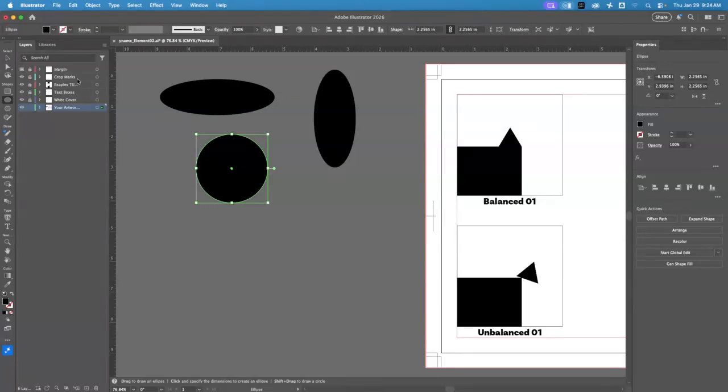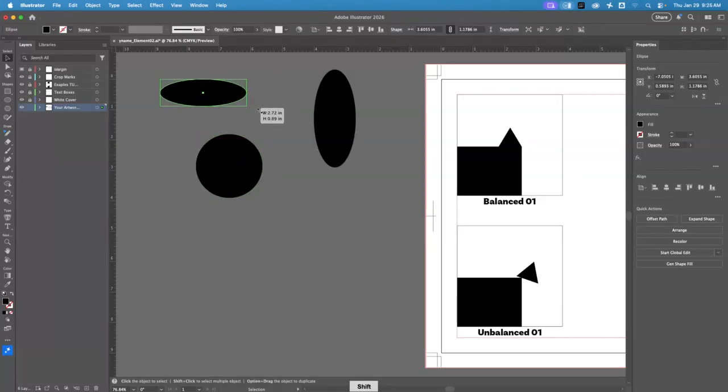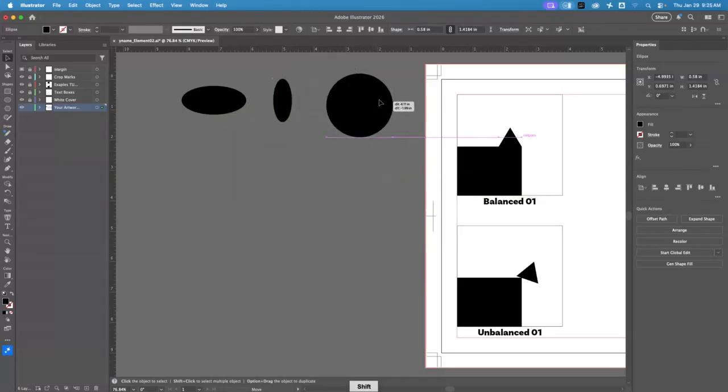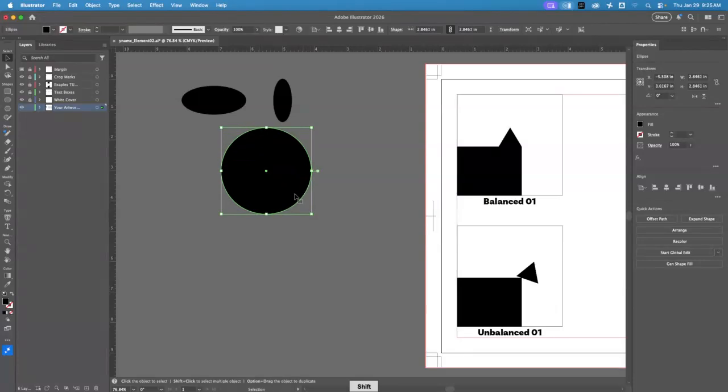And again, when you go to the select tool, if I want to resize it, I hold down Shift and I can move it. I can resize it with Shift, and I can adjust the size of it by not holding Shift. But for the most part, always get in the habit that your fingers are always hovering above Shift. Constrain it. If you want that shape and you want to keep it, just hold down Shift.